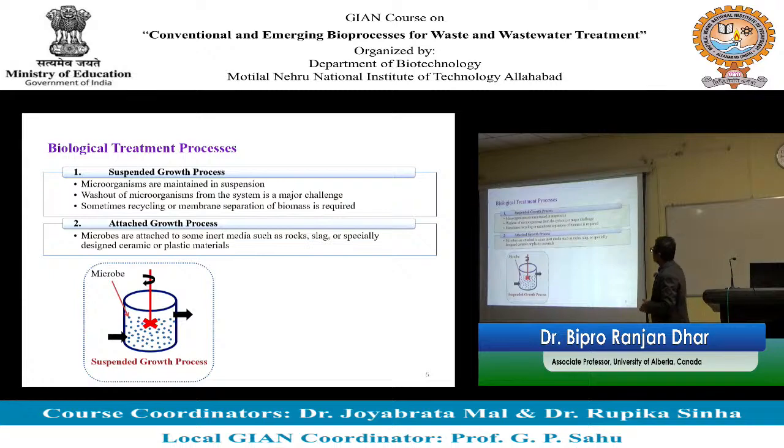When wastewater enters the system, it contacts the organics, and the microbes degrade them. The microbes are retained in suspension, but one of the major challenges of this kind of system is washout of microbes, because if you want to treat your wastewater, you have to make sure the microbes remain in the system.